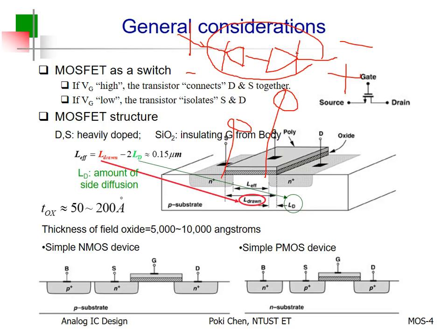And this is the definition of an enhancement type MOSFET. You need to enhance the MOSFET, otherwise it doesn't conduct anything. It needs to be off. But for what? Power saving. We need to save the power for the whole chip. So by nature, everything needs to be off, unless we would like them to be on. Then we apply proper voltage to the gate to turn it on.